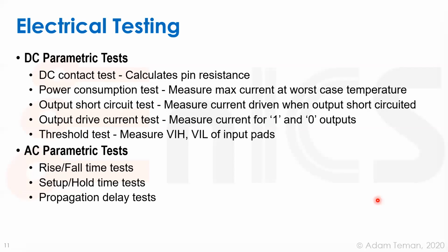And then of course you have the AC parametric tests, where you're going to measure the rise and fall times, the setup and hold times for the IOs, and the propagation delay of different signals that go out of the chip.